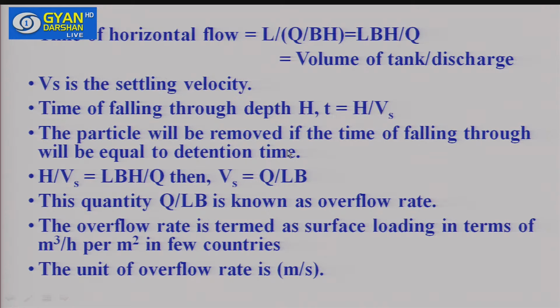The particle will be removed if the time of falling through is equal to the detention time, meaning the time for which water remains in the tank, and the time taken for a particle to settle to the bottom of the tank. If the time taken by the particle to go to the bottom of the tank is less than the detention time, then it will be removed.